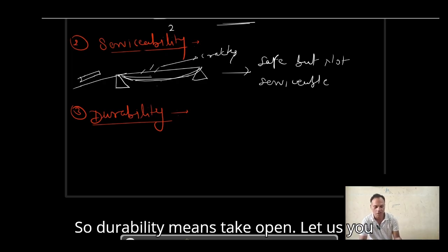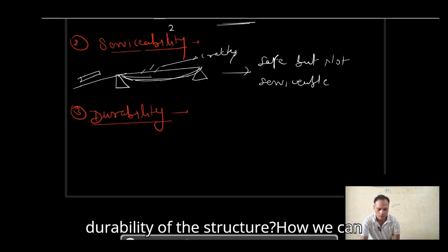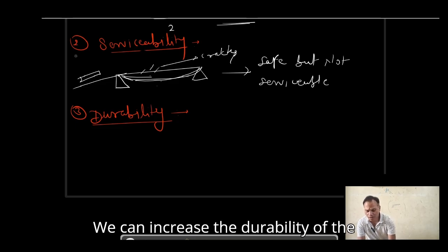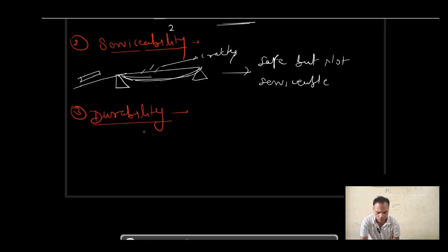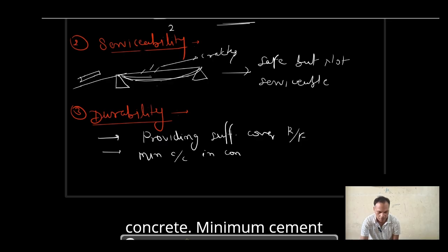So how can we increase the durability of the structure? We can increase the durability of the structure by providing sufficient cover to the reinforcement, and by providing the minimum cement content in the concrete.